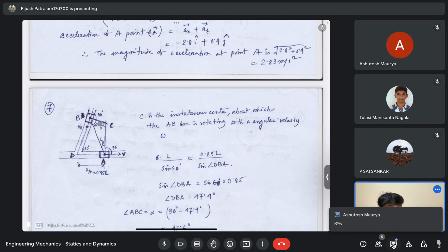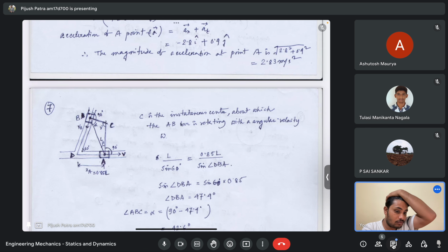So the velocity is R into omega, exactly, that is the case. When R equals 0, the velocity is 0, meaning the point about which it is rotating has zero velocity. In this case, point C is the point about which the velocity is 0, that means the instantaneous center of zero velocity, point C. You need to read this concept carefully in any textbook, but here I am just discussing it in the context of this problem.